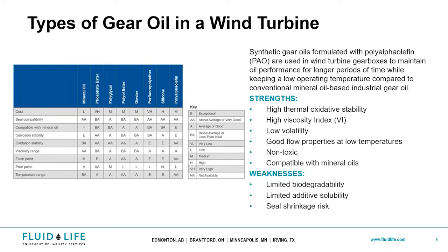So one part of the equation, of course, is having that non-firefighter mentality. You're analyzing problems both in real time, but also in preventative measures. So that's staying on top of maintenances, that's having other data to support your oil analysis, whether that be boroscoping or vibration data, as just some examples there.